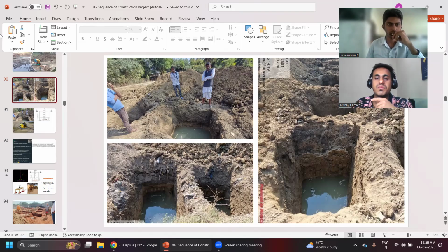Now let's say you're doing an excavation. You encountered water like this. How will you take care of this, being a site engineer? Sir, by the pumping method, the dewatering method. In dewatering there are many methods. We can use any method, but the pumping method is preferable, sir. Okay. How will you pump it out? Pumping you'll do, but from which excavated pit will you do the pumping?